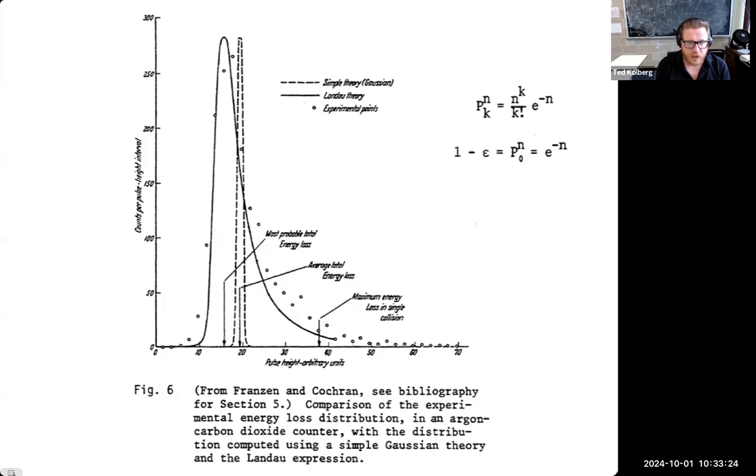So this has a couple of practical consequences for people who are designing these chambers. The first is thinking about the electronics chain that you want to attach to your wires. For a single channel, the dynamic range that the electronics has to absorb is significant. There's a factor of 10 or 100 between the lowest energy signals, which you might frequently see, and the highest energy signals that you might see. And this also has implications for the efficiency of a thin detector. If we're trying to detect particles while absolutely minimizing the amount of scattering off the material, for example, I might be driven down to extremely thin chambers on the order of 1 millimeter thick.